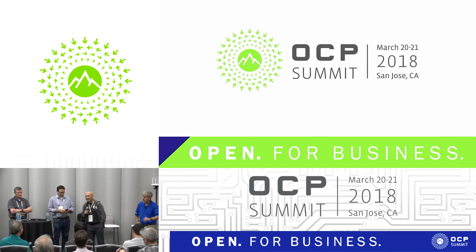Yeah. Just out of curiosity, what is your failure rate on CWDM4 pluggables? I'm afraid I don't know, or I cannot tell. But last year, when we were working on Facebook's optical supplier qualification process, I worked with multiple suppliers. We asked them to deliver their predicted FIT numbers or predicted MTBF, mean time between failure. That gives us the annual failure rate if you calculate it well.